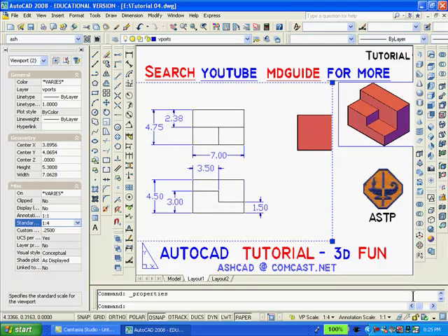You must remember that when using paper space, the entire drawing should be printed at a scale of 1:1. Even though individual viewports can be set to different scales, you set the scale of the large viewport by clicking the Properties button. The standard scale is found under Miscellaneous, and that is where you set the scale.